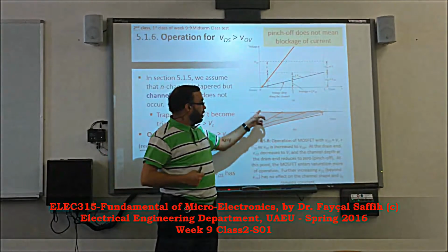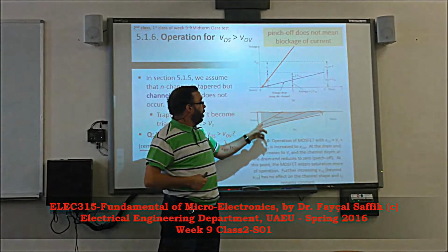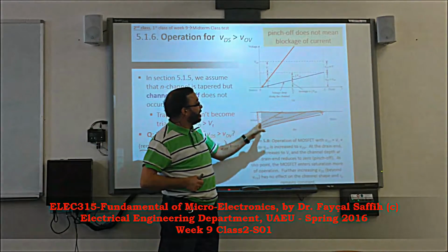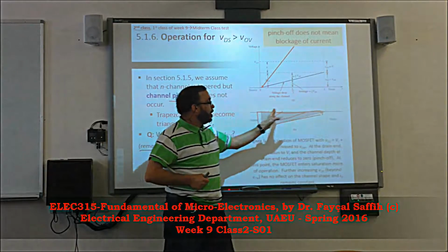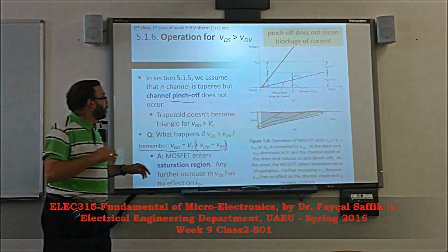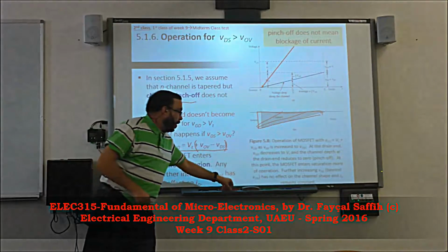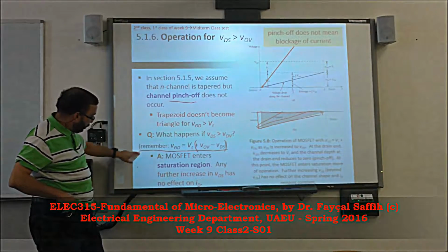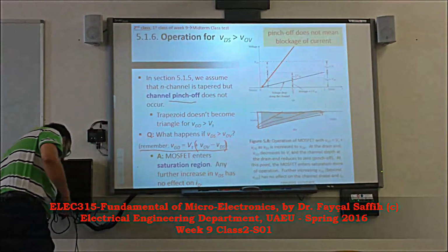But the base here stays the same, because V overdrive at this position stays the same. It doesn't get influenced by the drain anymore. So this is just to explain what's going on in the channel when VDS is above V overdrive.